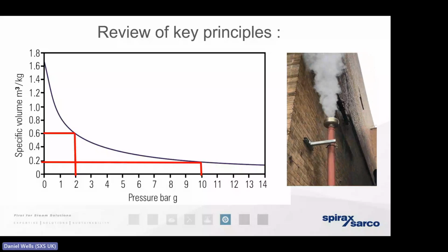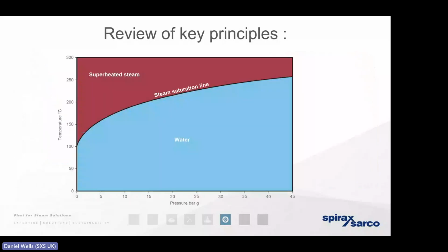Now, unfortunately, it's a necessary evil. We need to protect the infrastructure from that expansion. But what we can see here is a case where we're losing a significant mass of steam. So our inefficiency is going to increase significantly. And if we've calculated our cost of steam, we know exactly the financial impact that that single failed steam trap is going to have.